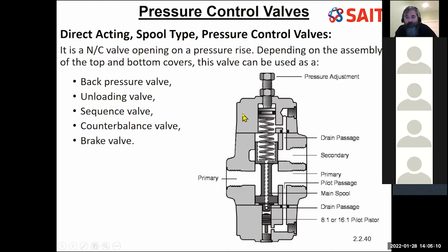So if I put this back on, the top piece on the other way around, well, this drain passage is not connected. Same with the bottom, there's a parting line that I can put on the other way around. I can take this apart and actually change the spool in the center. I can put on a different part at the bottom. So a Vickers valve actually comes with 5 different parts, and I can build with this over a dozen different types of valves.